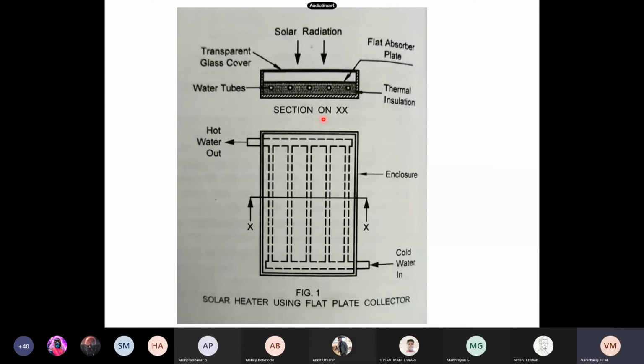And it is usually kept in an inclined position to absorb the heat energy. As I said earlier, the top cover is made of glass, and it is transparent to the incoming solar radiation. The radiation energy of the sun falls on the flat metal plate, whether it might be aluminum, steel or copper, which is the absorber plate coated with black paint, which has a high absorbing capacity. The flat plate is placed facing the radiation of the sun, and is inclined to the horizontal.